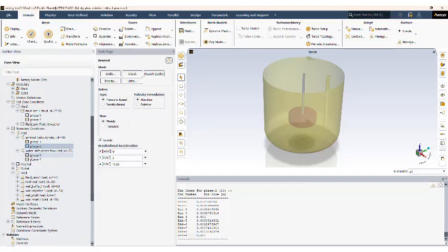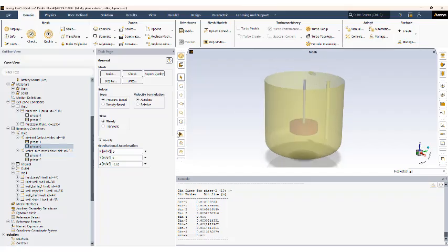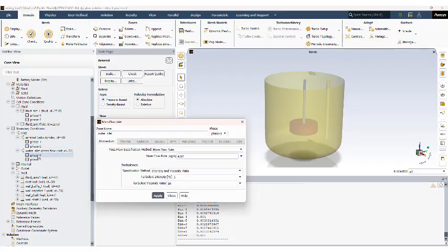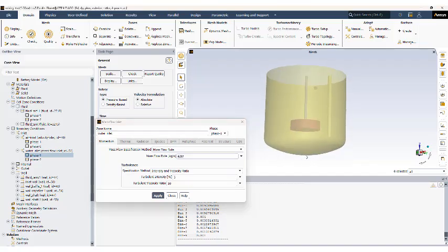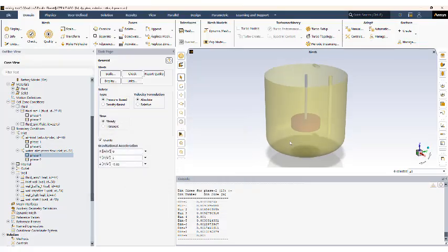Also, the water injection or the water inlet is set at the top of the domain, as I mentioned, and we can go into phase 1. That's the water phase. I set a mass flow rate of 6.57 because it matches closely with the expected flow rate at the bottom here of water, since we have water flowing at the bottom under a pressure outlet boundary condition. So basically that helps keep the continuity, the mass balance for water in the system. And that is basically it.